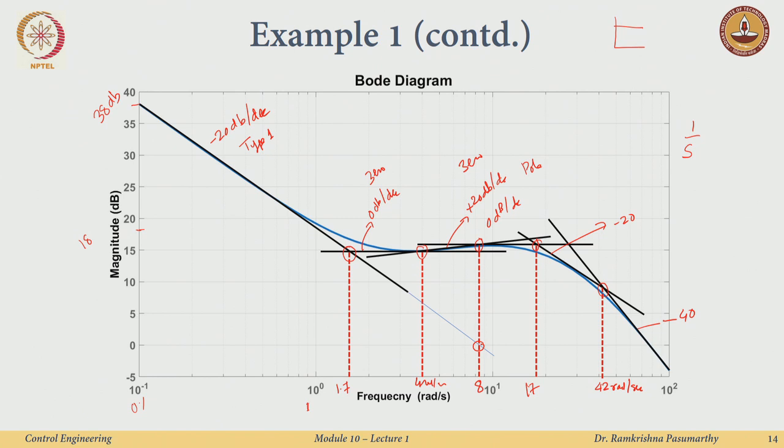We also saw this when we learned how to compute the velocity error constant through the Bode plot. So this is 8. My constant K, which sits in the numerator, where the initial low frequency region is of this form, is simply found to be 8 by the intersection of the initial line with the 0 dB line. Now things are straightforward, right?